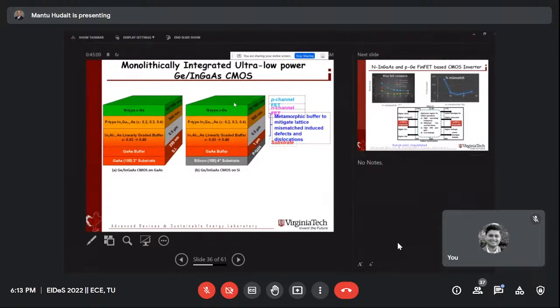Alternate CMOS, and it is better than the ITRS roadmap. Means the current FinFET has an aspect ratio, fin height to width ratio, please remember height to width ratio, of about 4.5. He told me, say 4. And I told him, can you do aspect ratio 1:1, meaning 1 height to width ratio, and show me that the circuit is good. Again, I'm not a circuit person, I'm a materials guy.